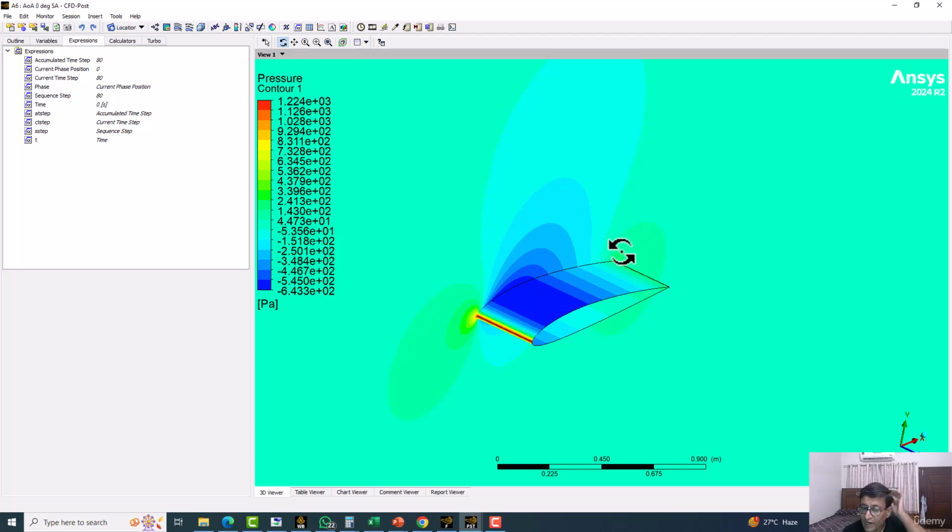So why are we doing this? Because when we divide by the area, this becomes a non-dimensional quantity, irrespective of the dimensions, the chord length and the span-wise direction. So this is independent of these values. Once we divide by 0.3, they are per unit area, so this is valid for any case. And if you want to calculate forces dimensionally, then you have to multiply with that area. For example, if my new wing is 1.3 meters, then I will multiply with 1.3, I will multiply with the 0.5, and the same thing here.